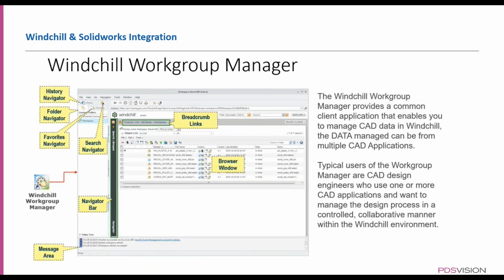Then the next thing that I mentioned is what actually integrates your Windchill with your SolidWorks. There's this tool here that's called the Windchill Workgroup Manager. It's a piece of software installed on the system, and it basically gives you the Windchill interface in there.